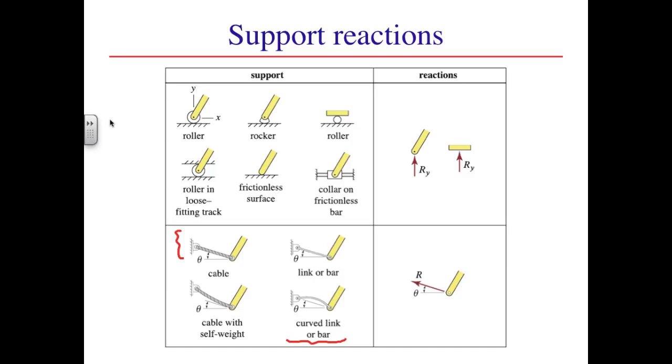There is great value in identifying a body as a 2 force member because such a body is automatically in equilibrium. If we do find ourselves with a problem where many different components are competing for our attention, it can be very useful to begin by identifying the 2 force members. This allows us to put these aside and focus on the remaining components.